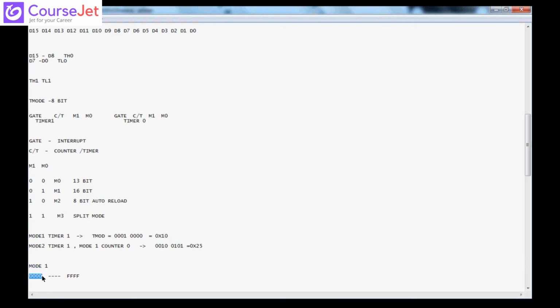We have to start the timer. We will have to say start also. And then we will have to wait for that overflow. In between, what is happening is nothing but incrementing, and that incrementing is nothing but our delay. But for that we need to tell our controller to start the timer, wait for the overflow flag, and then again stop the timer.